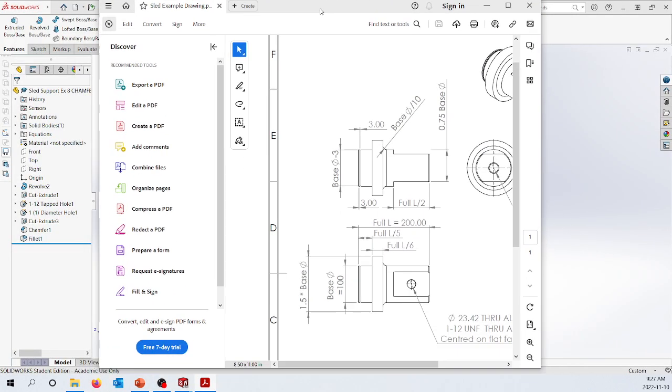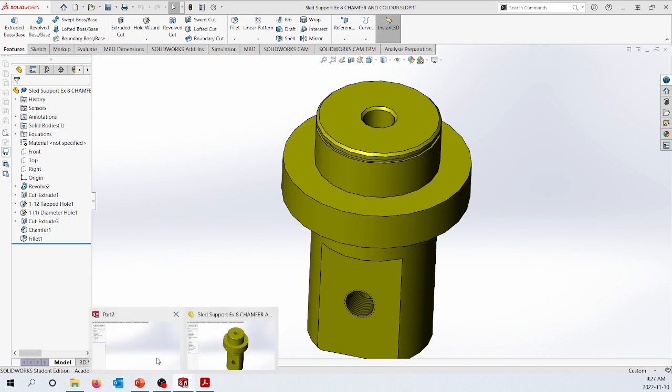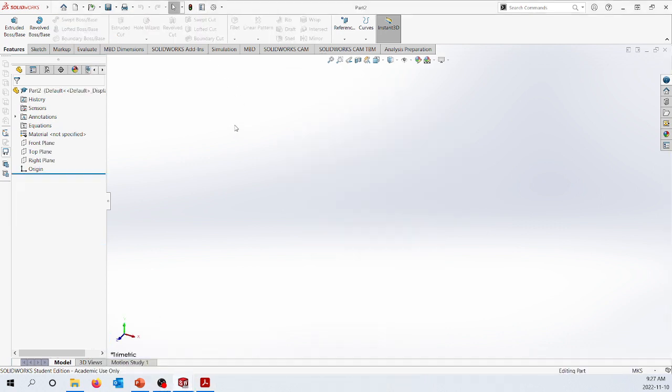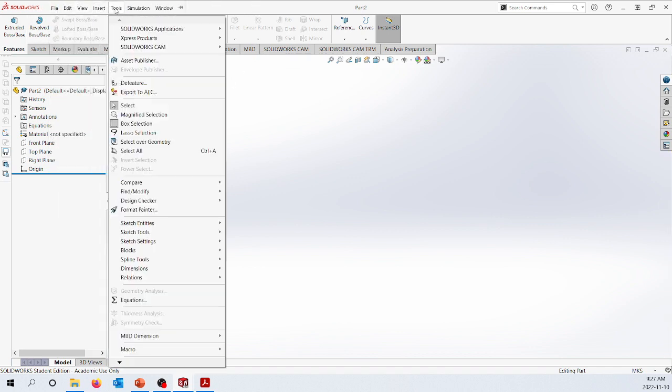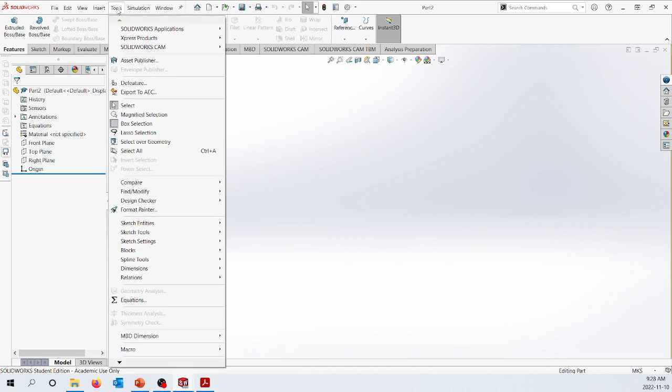So let's start with establishing how to make a global variable. Let me open up my new drawing. I have changed my settings so my equations folder always shows up here. I forgot how I even did that, so I couldn't remember how to undo it, and I'd have to Google to get rid of it. But for you, if you go up to the top here, under SolidWorks, let me pin this open actually, I prefer that pinned. Under Tools, there is this Equations.